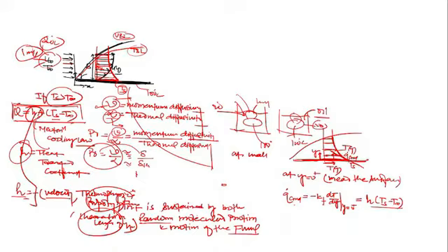Yes or no? Because the value of the heat transfer coefficient is going to vary if we increase the velocity, if we change the density, if we change the shape and orientation and all. So if you get the value of h for the prescribed problem, then convection heat transfer is a very simple problem. Just put the value of h and A and all the parameters, then you can solve.